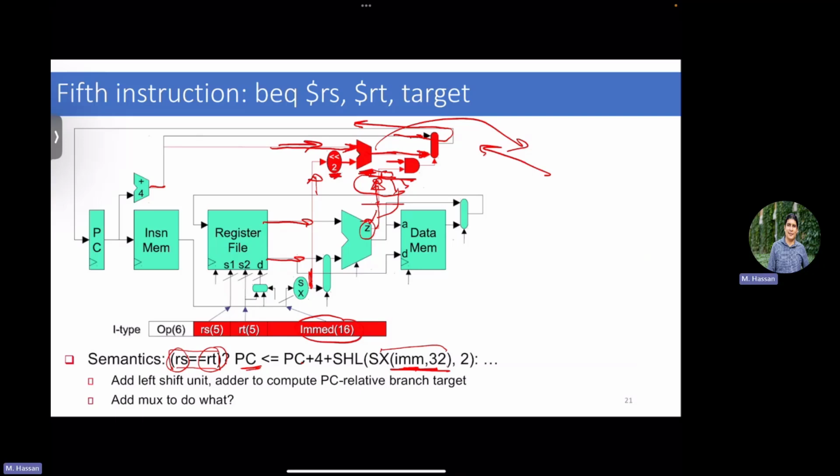And then you simply take the last 4 bits of your program counter, because you have 26, 28, and then 4 bits of your program counter, and you load it to your program counter. How do I do this? Well, I take the immediate value, and then I shift it by 2. I go here.